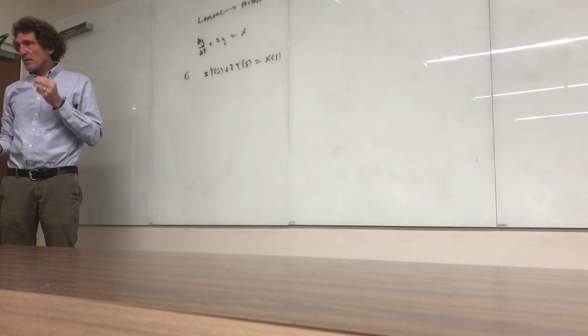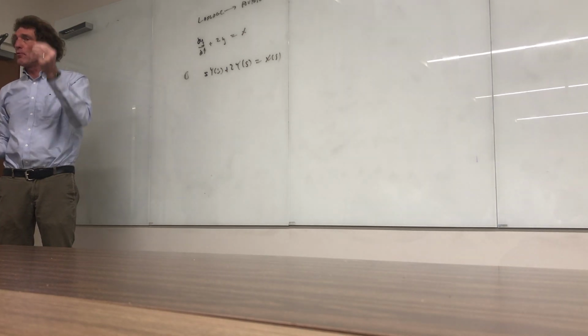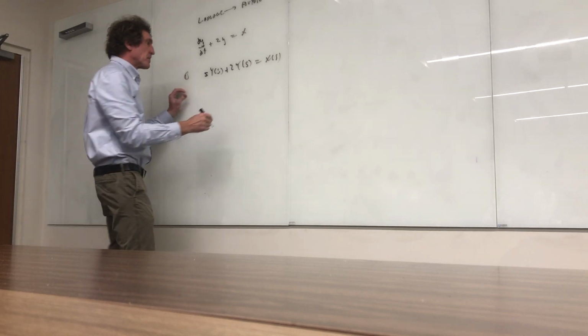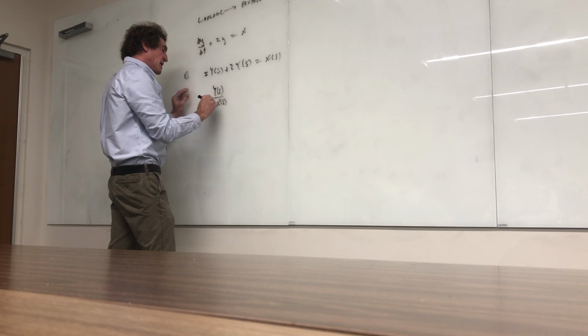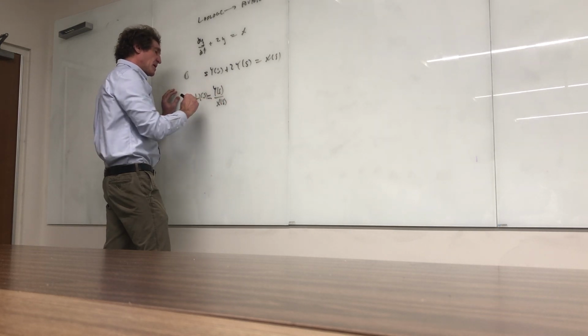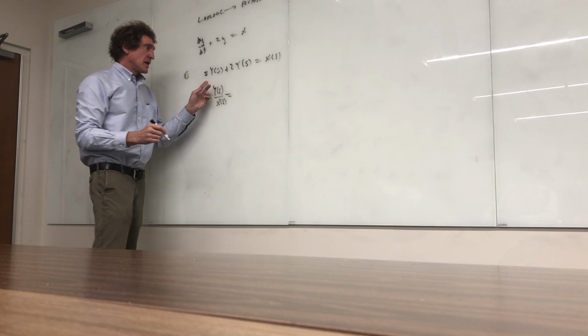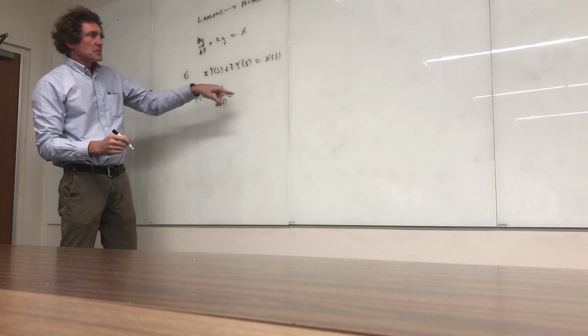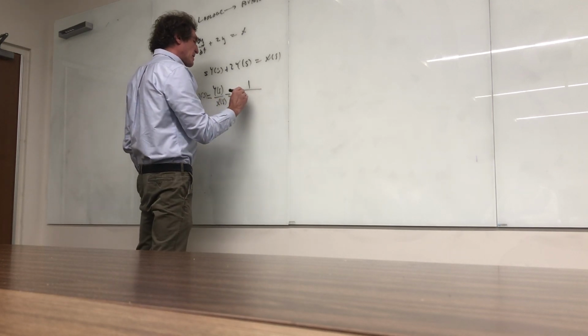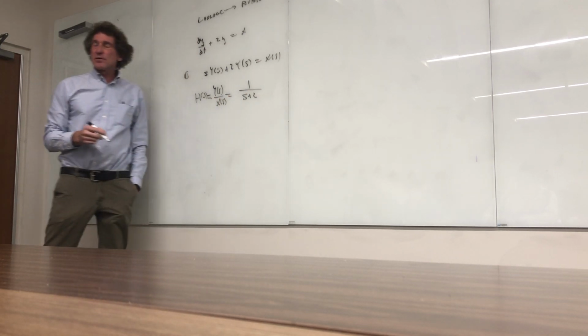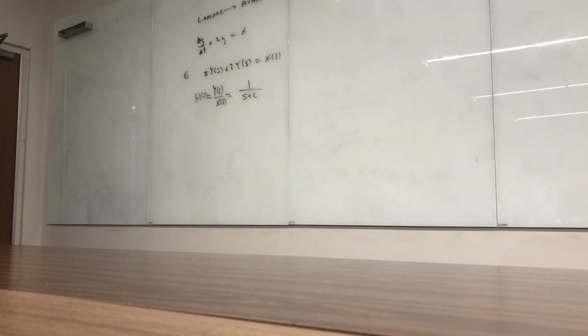After that, they want the response, which is the ratio of output to input, called the transfer function. So now what we want is Y(s) over X(s), and we term that H(s). If you look at this, I factor out the s plus 2 and divide by X(s), and I get 1 over s plus 2. Make sure you understand the steps I've taken. This is a very straightforward problem you had in your differential equations courses. You all agree?